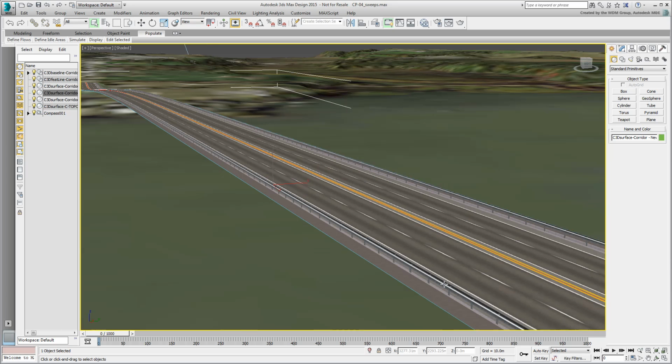Obviously, to create the geometry you need, you have to rely on some kind of lofting or sweeping process. These are techniques you could use on their own. Lofting is a geometry creation process, while sweeping is modifier-based. Better yet, you can rely on Civil View's Swept Object tool that makes the process that much easier.